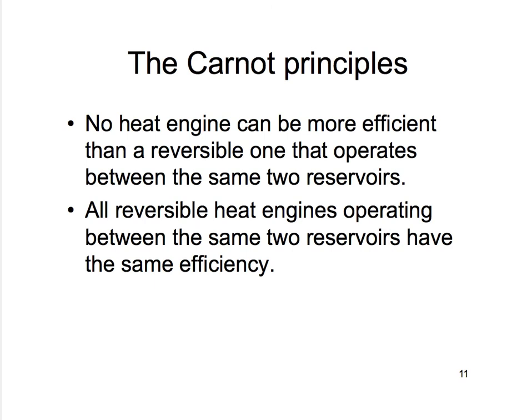Okay, next we're going to talk about the Carnot principles. Remember, the Carnot cycle is a reversible cycle. The Carnot principles are these. There are 2 statements. The first one is no heat engine can be more efficient than a reversible one that operates between the same two reservoirs. The second statement is that all reversible heat engines operating between the same two reservoirs have the same efficiency.